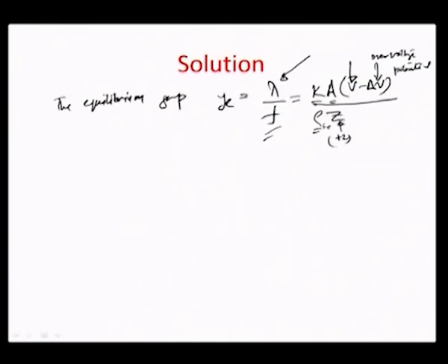So, iron can be removed mostly at +2, so it is a ferrous state that we are removing, times 96,500 coulomb, which is the Faraday constant F, and times the feed rate, which is given to be 2 millimeters per minute. Okay. So, if I am able to calculate the equilibrium gap this way, just plug the values,